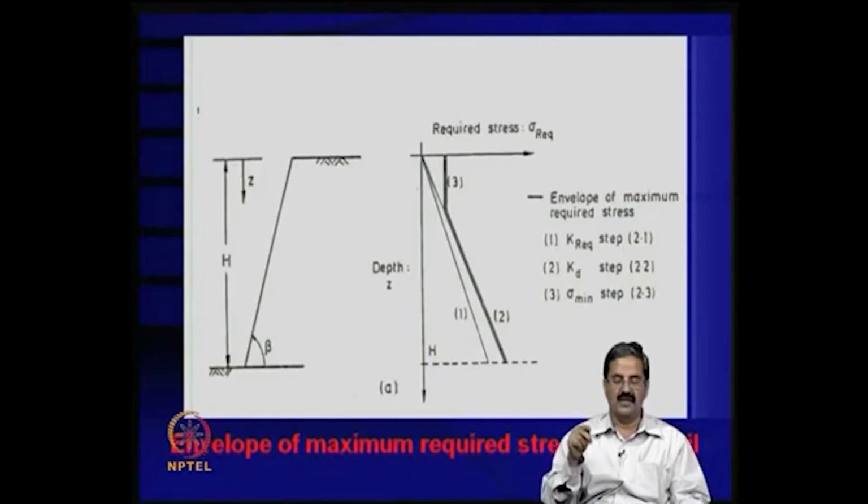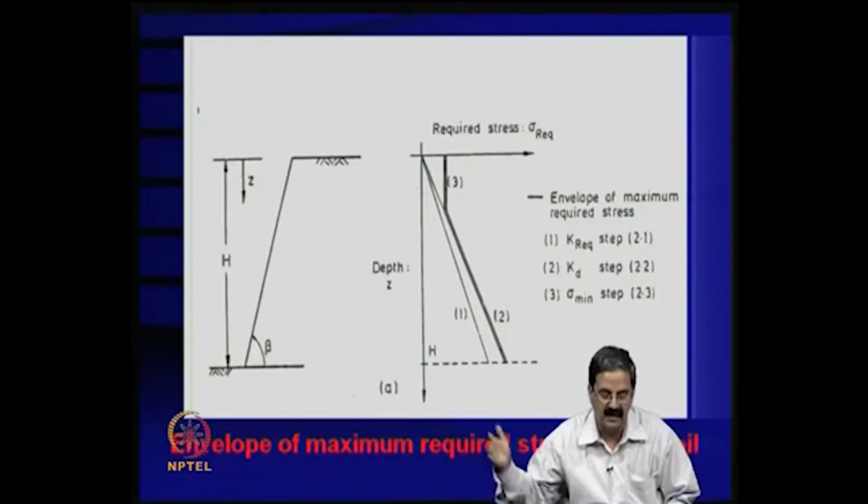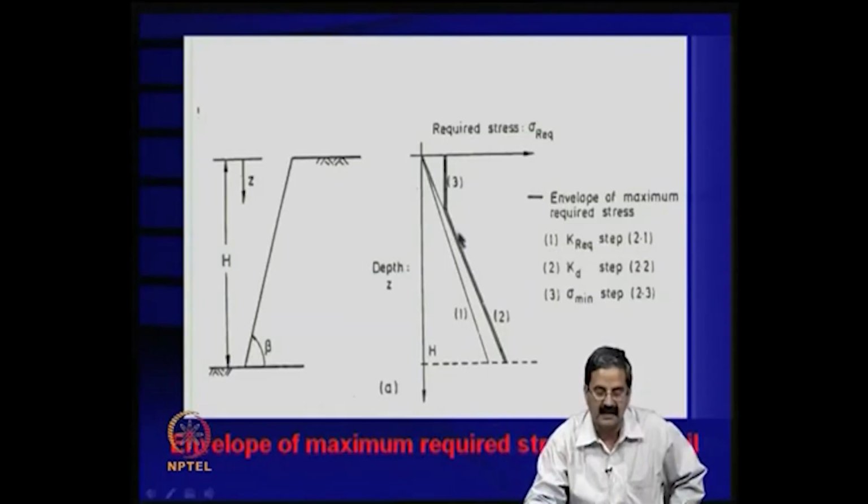So, what we should do is assume that the whole force is acting, but there are some small changes here. There is a second one, which is that from bond and reinforcement angle considerations, there is a small correction factor you have to put in, because of which the required reinforcement force will be a little higher.